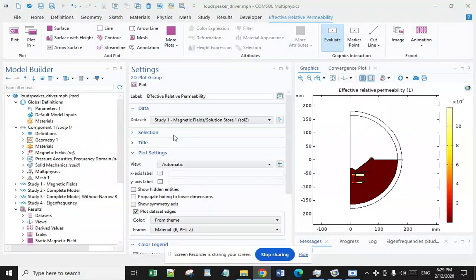The electric coil is driven with an alternating current electric signal at ultrasonic frequency, typically in the range from 20 kHz to 10 MHz based on the application needs. The signal can be a continuous wave, a spike pulse, or a tone burst signal. The electric coil with alternating current also generates an AC magnetic field. When the test material is close to the transducer, ultrasonic waves are generated in the test material through the interaction of the two magnetic fields.